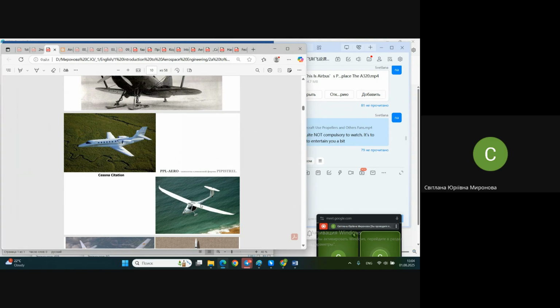This one or that one? Certainly not this one, because it has convenient flutter parameters, let's say, of configuration. It's a less stiff wing in this case. It's the best glider. It has less aerodynamic drag and higher aerodynamic quality. But in this case, the structure isn't stiff.